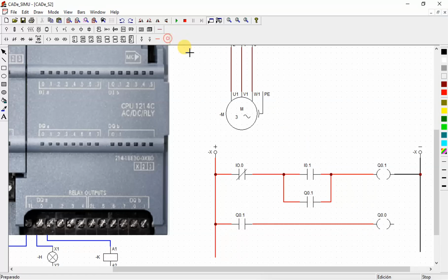Now with a PLC, this ladder logic is not wired, but it is programmed and fed inside the PLC. It depends on which PLC we have. For Siemens, we have TIA Portal, we have LS PLC, that is RSLogix. We have Mitsubishi PLCs, we have Omron PLCs, they use CX-Programmer. It depends on the PLC that you're using, so you have to get the basics on how to use those softwares.